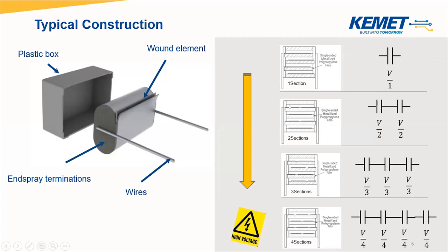This is the typical schematic of a two series construction, where the first film is connected to one polarity and the other polarity through a bridge inside without metallization, and the other film is completely metallized in the middle with two offsets of non-metallized part here and here.